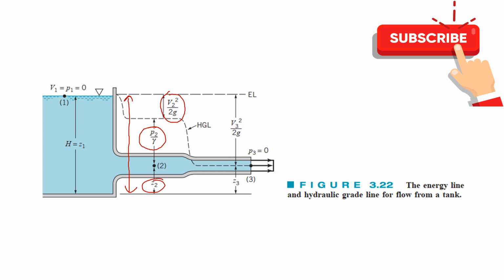So this represents our total H, that is our total head, and this represents our hydraulic grade line, and this total represents our energy grade line, that is the total energy that was inside this fluid when it was contained at a height h1, then it flowed, then it was steady at point 2. At point 2, some of this Z, this elevation, got converted into pressure, and it came down to this level, and this amount of head got converted into velocity head.